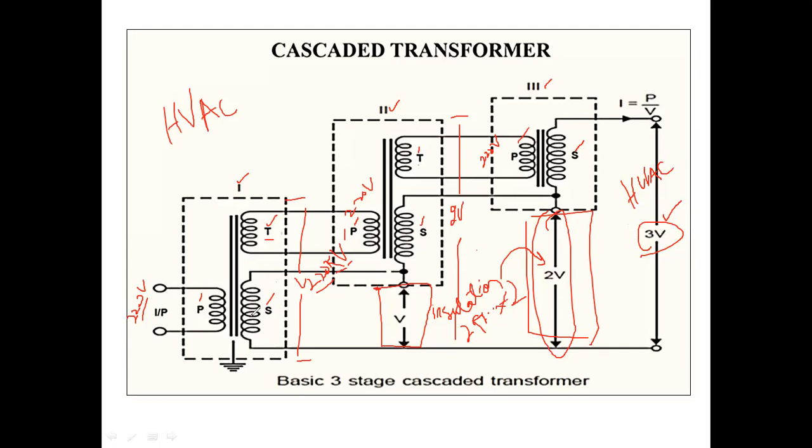First of all, if a fault occurs in a transformer and we have only a single unit, the whole system will be disturbed, because the whole generation is dependent on that single unit. So if the fault occurs in that single unit, the whole system will be stopped.